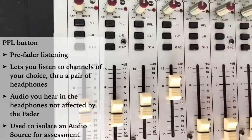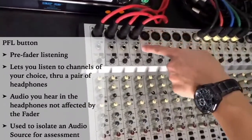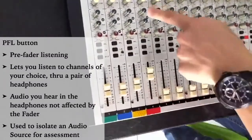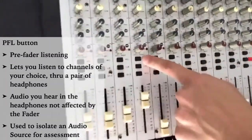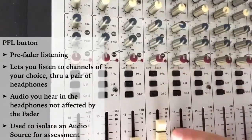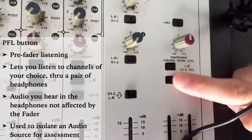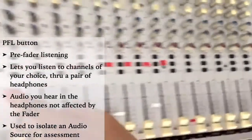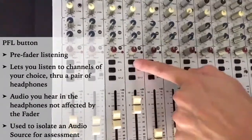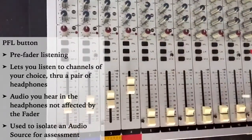PFL means pre-fader listening. You remember that I said the audio comes from here, all the way down, and then finally comes to the fader. So before you reach the fader, you reach the pre-fader listening. When you press it in, you can listen to the audio before it reaches the fader. When you push both of these down, you can listen to whatever you select on PFL only. So if I deselect the PFL, now I cannot hear myself in the headphone, though you can hear in the video. Now if I select this one, then I can hear myself in the headphone.